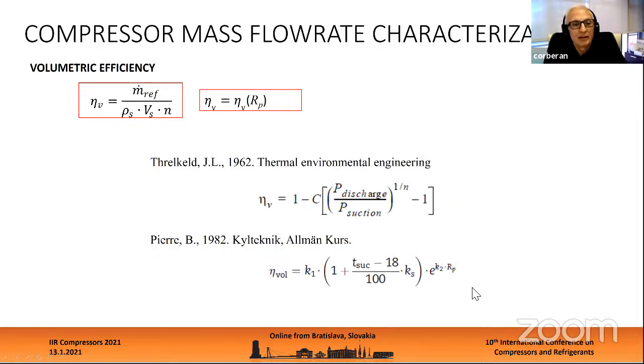If we want to characterize the mass flow rate, ideally, the most important thing is to try to do it non-dimensionally. The non-dimensional mass flow rate is, as a matter of fact, the volumetric efficiency that we all work with to characterize the compressor performance.